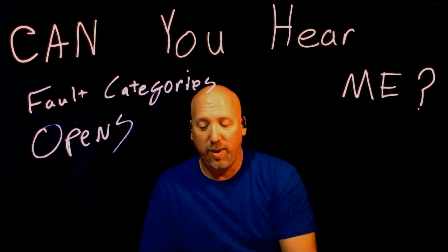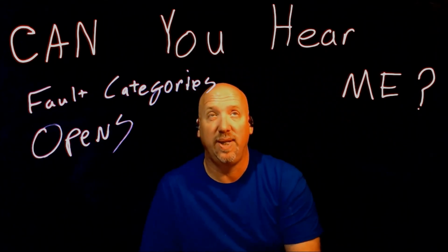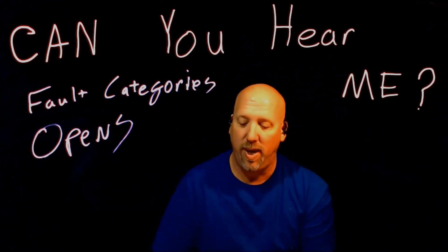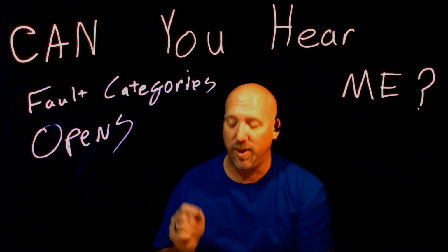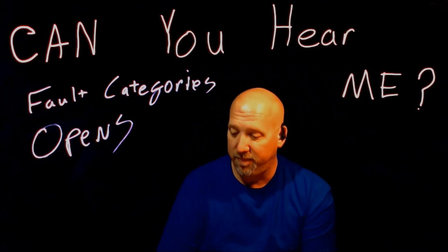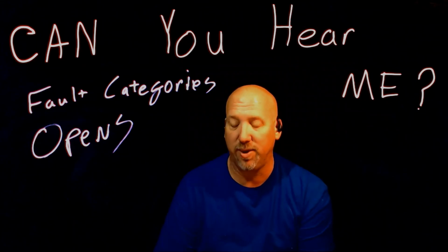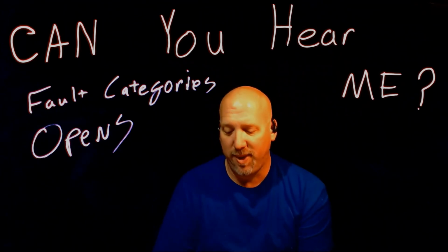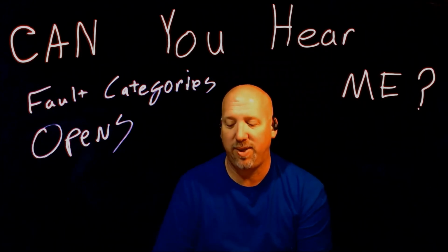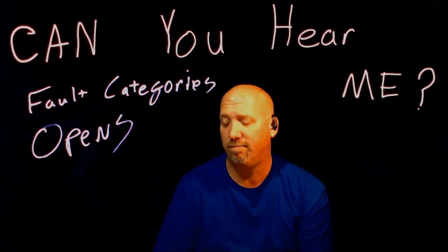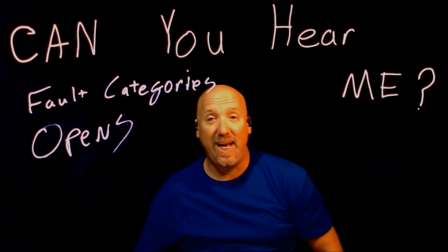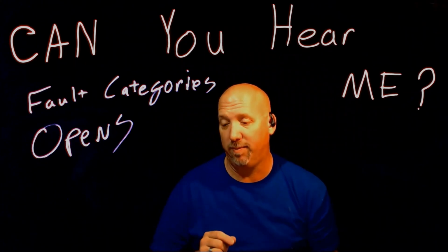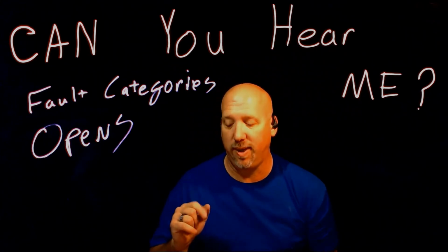If the module is not currently on the network, but is physically accessible, the test that gives the most information with the least effort is to check for network activity at the module itself. If there's activity, then it's simple to assume the network is fine and the module is not communicating. However, what if the network is open somewhere else and the module is sending messages that simply aren't getting to their destination? Whether the module is dead or the network is open, you'll still have network activity. So one more test is needed.